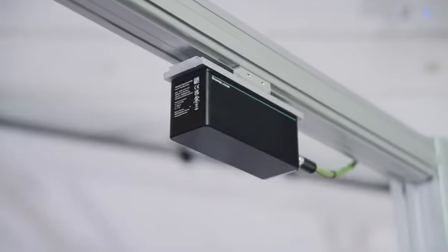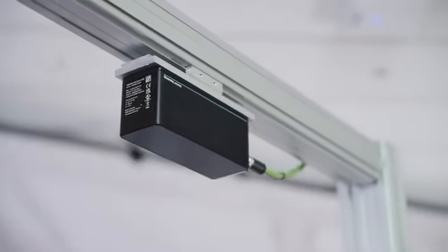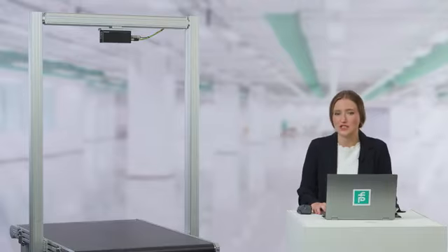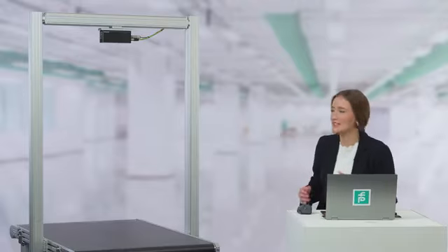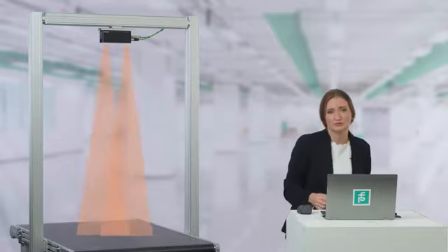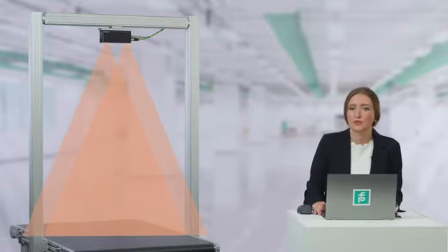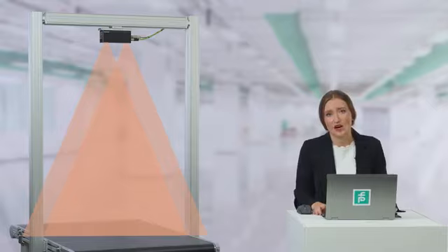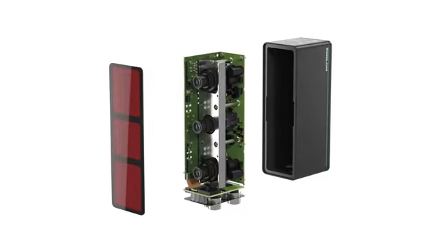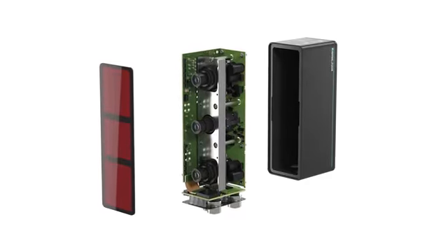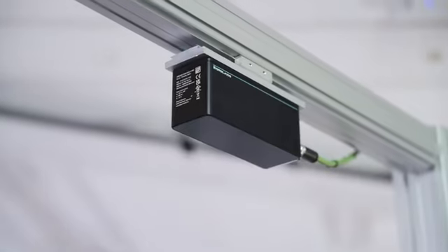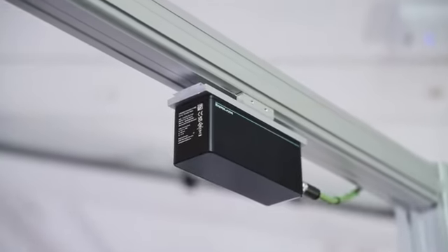For this demonstration, we have already mounted our SmartRunner above a conveyor belt. The technology we use here is stereo vision technology. This is based on two 2D cameras integrated into the sensor, one on the left and one on the right, that capture 2D images of the scene from different positions. At the center of the sensor is a projector that casts a unique pattern onto the scene. This pattern supports the matching of the two 2D images, which then creates the depth image, the 3D information.